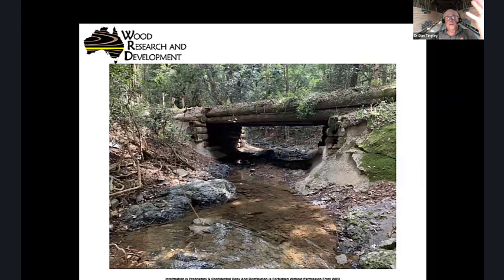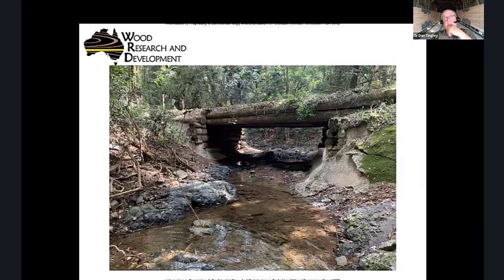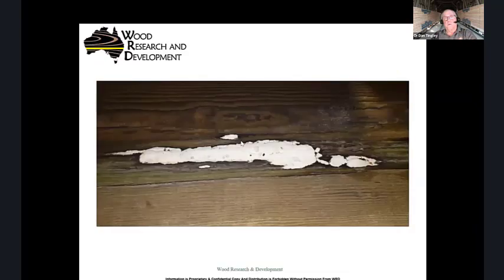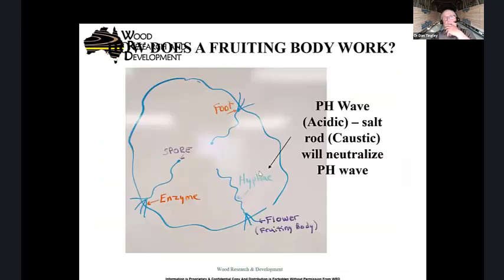So if I've got this timber bridge from Queensland Plantation up in Queensland, and I'm letting all kinds of vegetation grow around those logs, it's holding moisture. The moisture's in there. I've got vertical bolts in here. It's letting moisture in the middle. Vertical bolts here. Guess what? They're decayed. That foundation abutment is gone because it decays and goes away. Well, that's not wood's fault. We're putting verticals in it to allow decay to take place so that this fruiting body can grow.